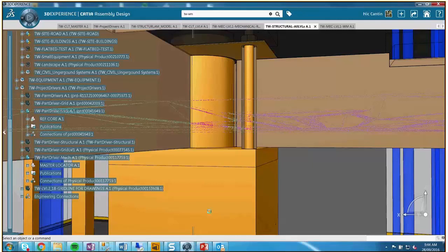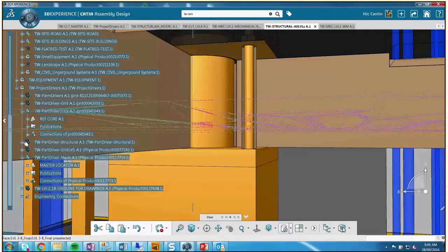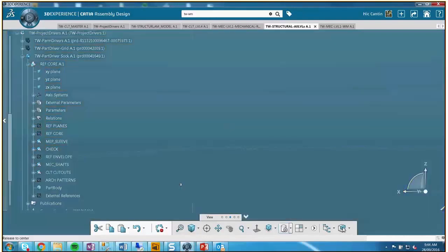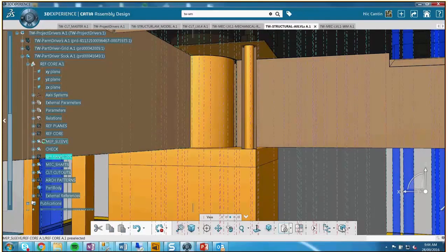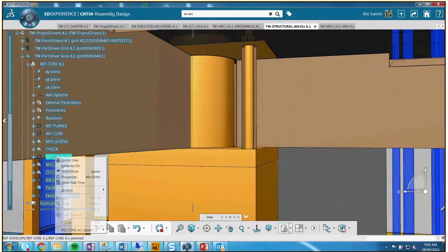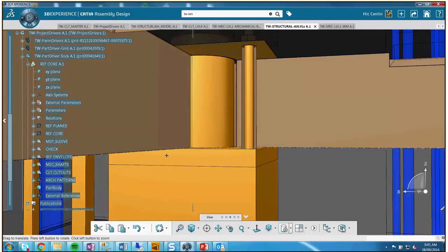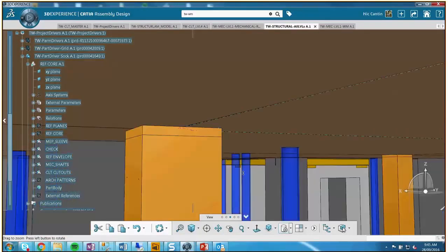Show mechanical. Are they prefabbing the interior walls in the next iteration? We actually have another one we're just starting, and that's our recommendation so far: to try to find a solution where the wall is fabricated with pipes in it and maybe one level of gyp off, so the plumbing code inspector can review on site, but you just have one side of gyp to close off.